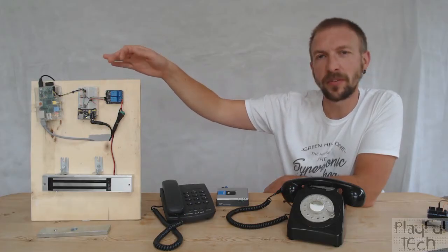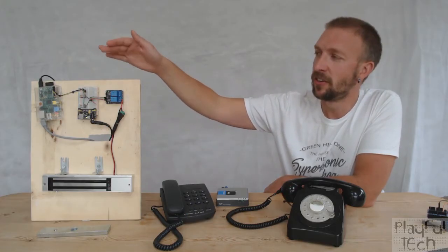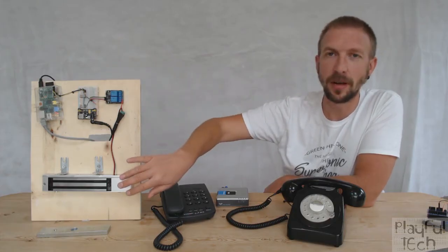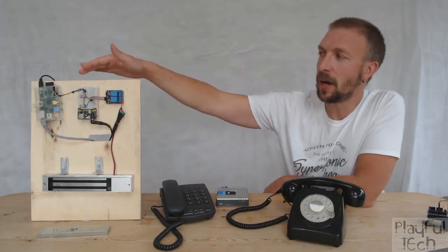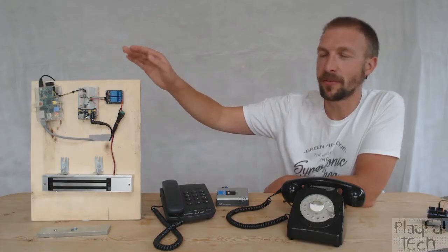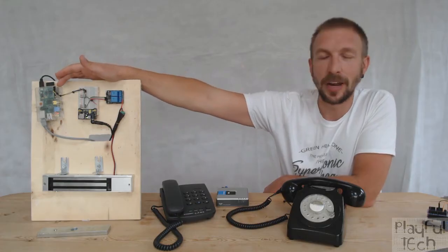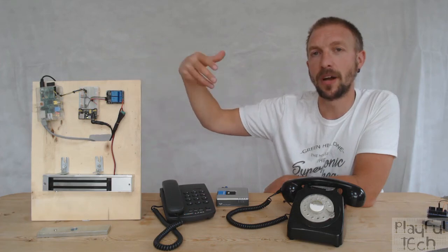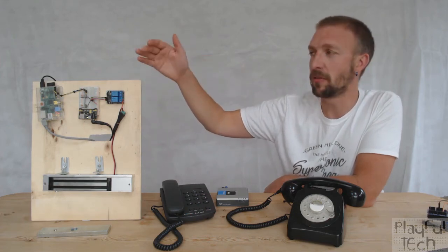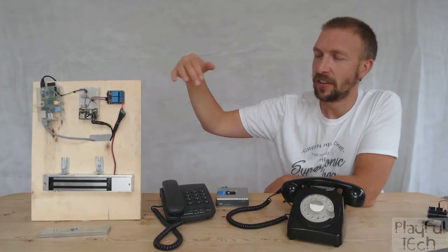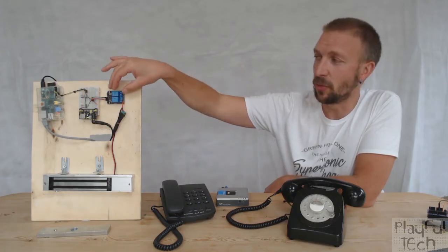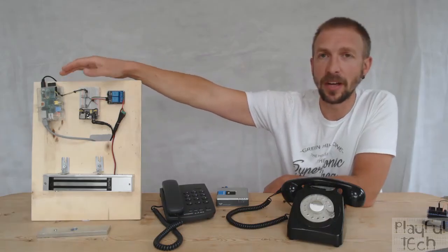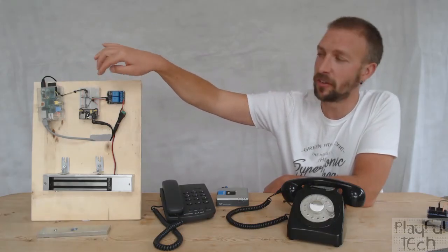You might have seen in my previous videos I've used Arduinos to control relay modules like this to activate maglocks. The Raspberry Pi is doing the same job as that. The only difference is that the Raspberry Pi input and output pins operate at 3.3 volt logic, whereas an Arduino Uno or a Nano or Mega runs at 5 volt logic. So what that means is an Arduino can control one of these relay modules directly. The Raspberry Pi, however, you need to have this kind of intermediary stage in the middle. So that's what I've got here.